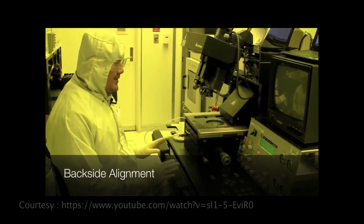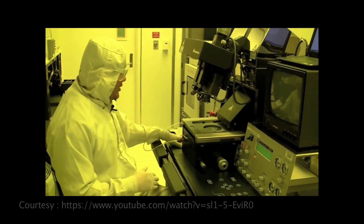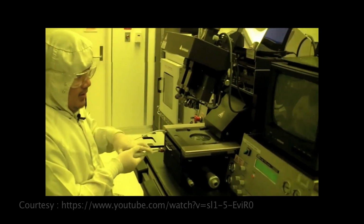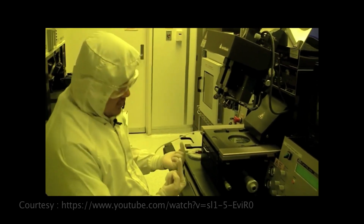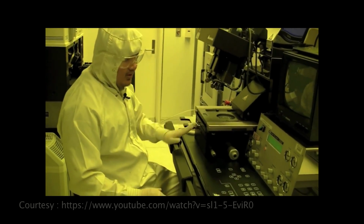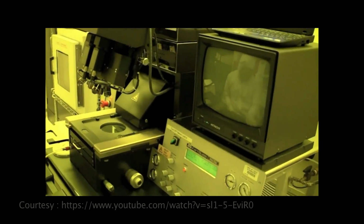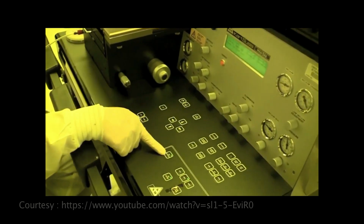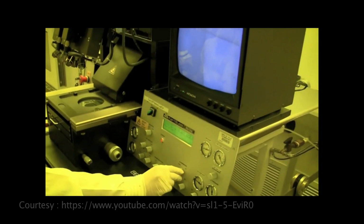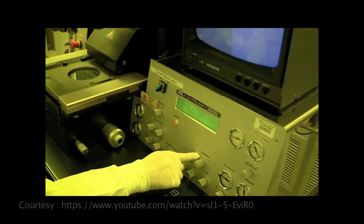We're going to be doing a backside alignment now. So what this does is it aligns features on the back of your wafer to your mask. And how you do it is with the microscope from the bottom. The first thing we do is we have to have our mask loaded, and then we turn the screen on, and we make sure this thing says backside alignment microscope is on, so it's on. But also we need to change this to backside alignment. So it can be either a topside alignment or it can be a backside alignment.